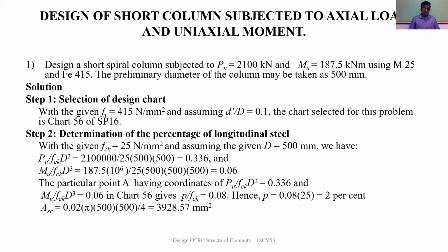The three sets of charts have fixed values of d dash by D. However, in practical designs, the d dash by D ratio may vary from those values. In such situations, intermediate values should be determined by linear interpolation.